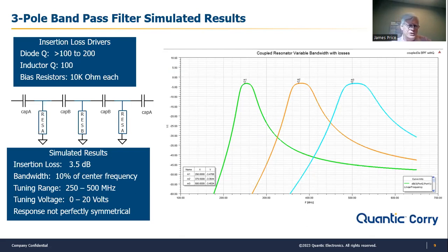And the reason why, just not to get too technical, remember how I said the resonators look capacitive above resonance? So if you look at this circuit above resonance, it's a series capacitor, capacitor to ground, series capacitor, capacitor to ground, etc. It's really just a capacitor. And a capacitor provides you 1 0 at infinity. So on the right side of the filter, it tapers off a little bit longer than it does on the left side.